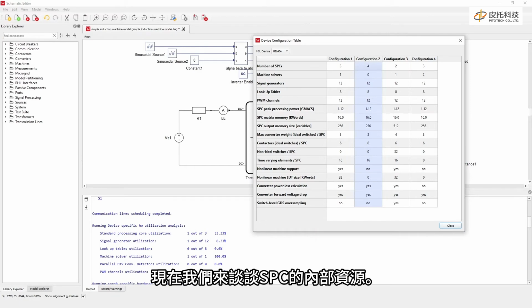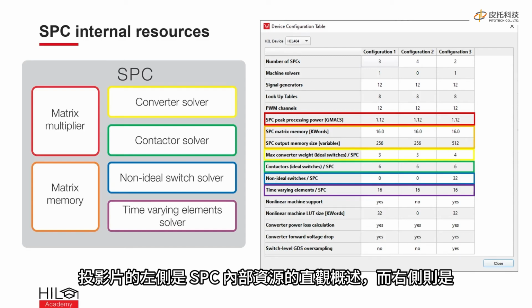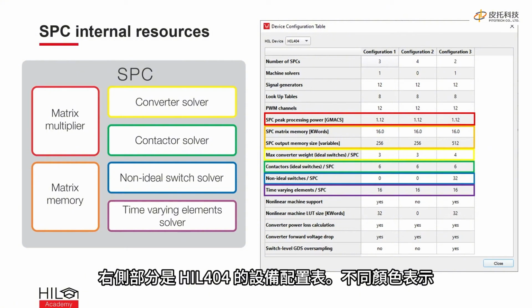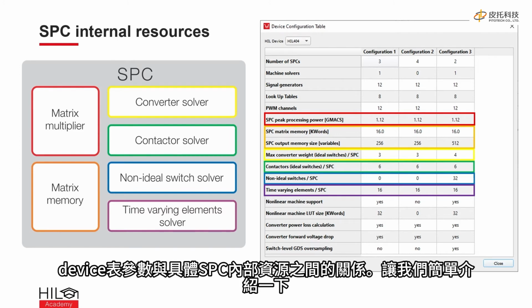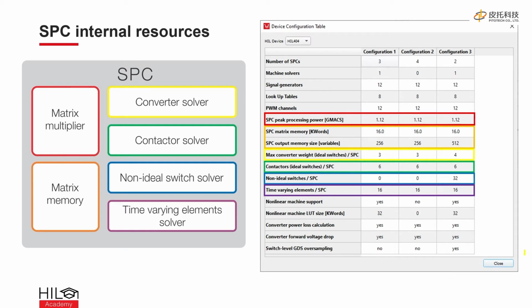Let's now talk about the SPC's internal resources. On the left part of the slide, there is a visual overview of SPC's internal resources, while on the right part we have the device configuration table for HIL 404. Different colors indicate the relationship between device table parameters and specific SPC internal resources. Let's briefly talk about Typhoon's approach to converter modeling before taking a closer look at the converter solver.